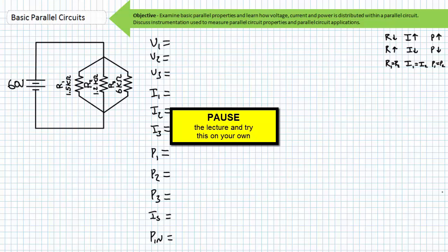The smallest resistor in a parallel relationship should dissipate the most power. The largest resistor in a parallel relationship should dissipate the least amount of power. Equal resistors in a parallel relationship should dissipate equal amounts of power. Power input should always equal power out. You can always use Ohm's law, and you can use any permutation of the power equations. Off you go. Have fun storming the castle.